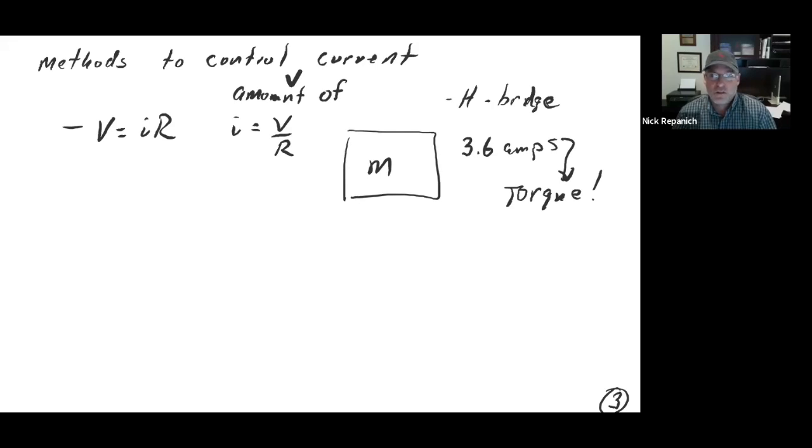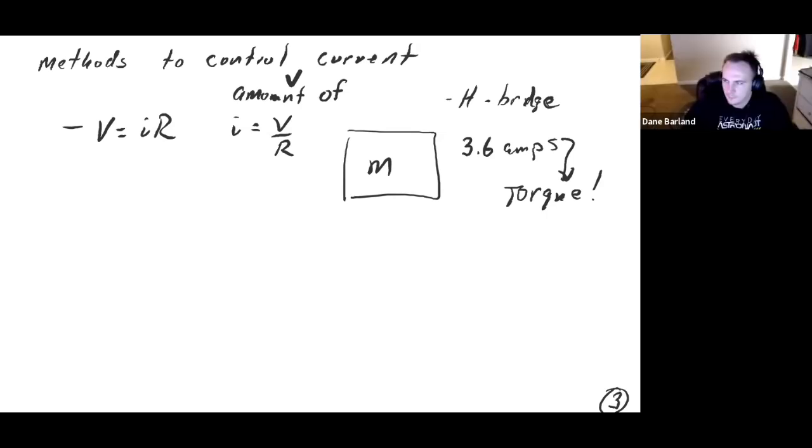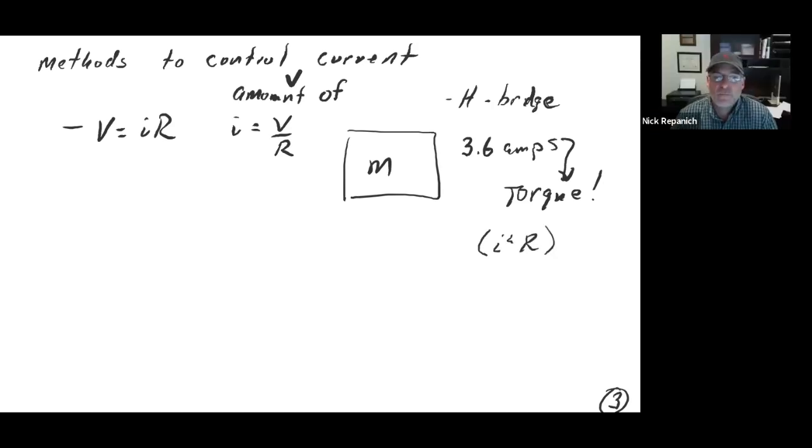It responds to current. What's the downside? What's it going to do? It'll heat up more. Yeah. You're going to burn it up. If they could have put in 3.8 amps, they would have. They have incentive to give you good speed torque curves. That's what they compete on. And they said, no, you got to give it 3.6. What if you don't have 3.6?